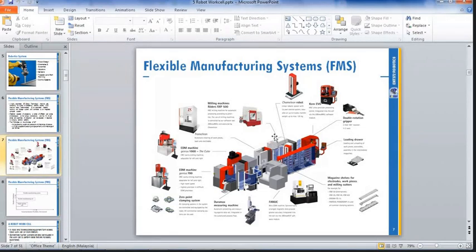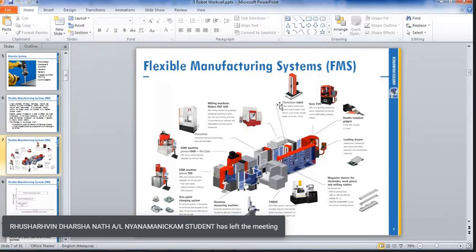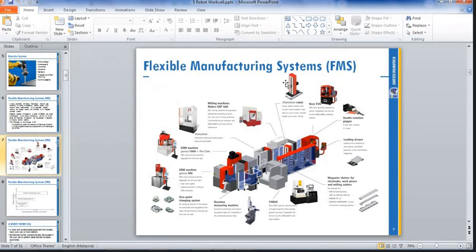Maybe you have an oven to cure the product, and then you have something like this elevator. They call it an elevator, or input and output loader. In the semiconductor industry, they call this an elevator, and the product that you put on this elevator, they call a magazine. It is something like a tray, but a magazine, because your product is built on a frame, so the frame will be slotted into the magazine. So you have an input magazine and an output magazine, and your product will be sent piece by piece through a conveyor belt. You can see a lot of this in industry when you go on internship next semester.